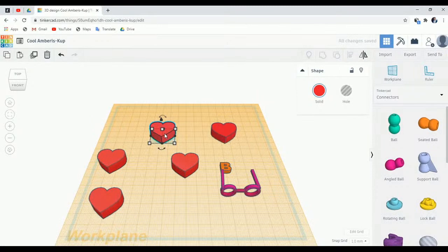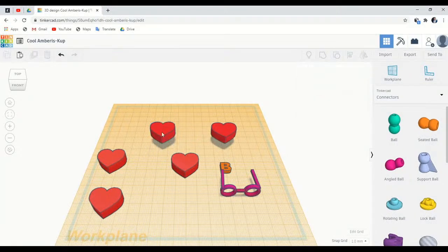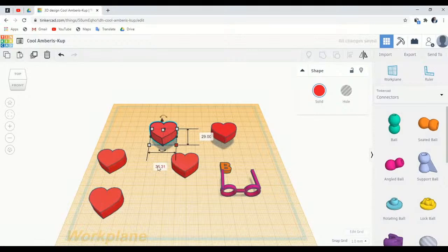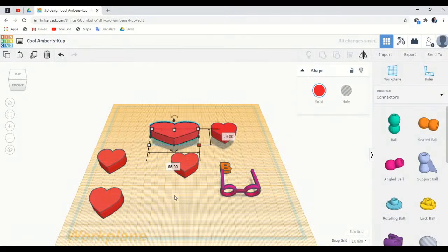Alright, you can also set the width, the height, and the depth because they are 3D objects. To select the width and height of this object, ensure you have any anchor points. These are called anchor points. Ensure any of the anchor points are selected, and then you can adjust accordingly. You can either adjust by moving the anchor points, or you can adjust them based on a number ratio. For example, I have 30 here. If you select 30, you can change the number to whatever number you want, and it will automatically apply it. So I can select this anchor point and then edit this number.